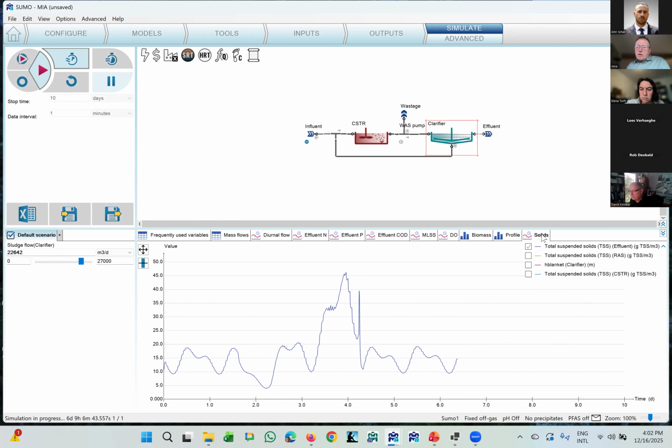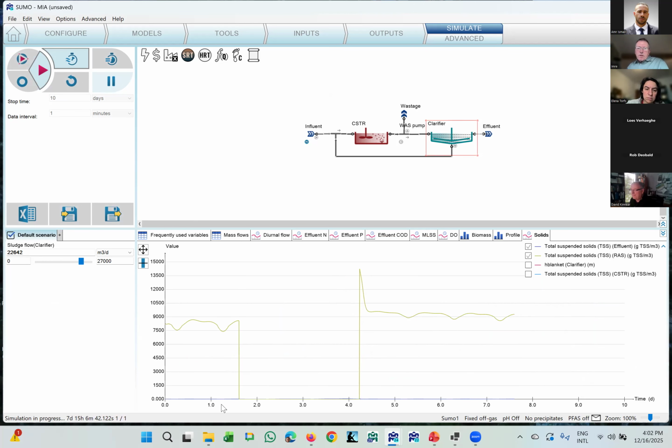And the effluent solids concentration came back. The RAS, where is the RAS? Here. There was no RAS return concentration during, well, this was like a 2 to 3 day breakdown, so it's pretty serious. That will depend a lot on the loading of this clarifier. In our examples, this is just a standard example that I pulled up, and it's over designed because we're demonstrating normal operation.